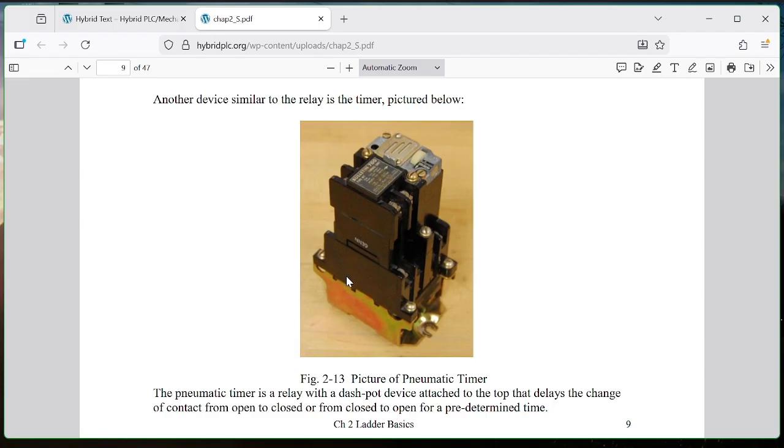Now, why would anybody use this? Where would this be used? When you need a delay of time, you would use this. But how much does this cost? $100, $200, okay? It would have to be wired. If you look at a PLC timer, it's something that you can put in a time delay inside a program controller, and you get that time delay doing the same thing, and it's more accurate than this. And it also doesn't cost you a lot of money.